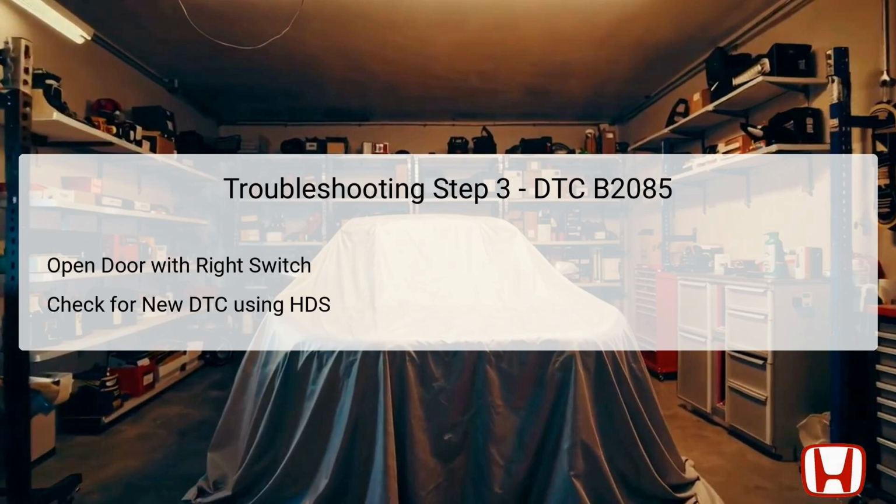In this step, you will open the right power sliding door using the designated switch located inside the vehicle. The action of opening the door will allow the system to detect whether the half-latch switch is functioning as intended. Following this, it is crucial to check for any new diagnostic trouble codes using the Honda Diagnostic System, HDS. If the DTC B2085 is displayed again, that indicates that the issue with the half-latch switch or its associated circuits persists.